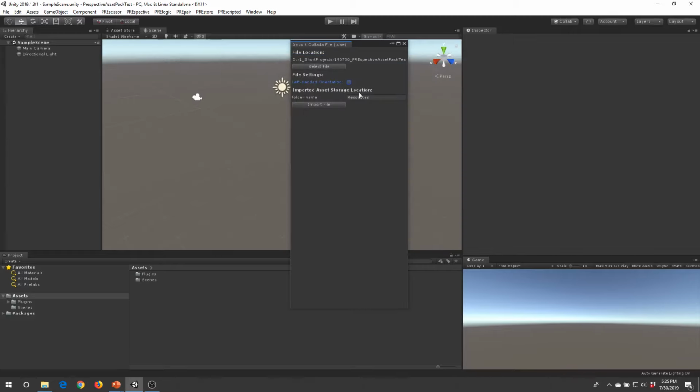Down here are some settings. Most CAD files are provided in a right-handed orientation, but if you were to come by one in left-handed orientation, you can set that here. Furthermore, after importing, the file will be buffered in your resources folder, so you can set a target folder here. By default, it's resources, but if you would want, you could store it somewhere else. So let's start by importing the file.